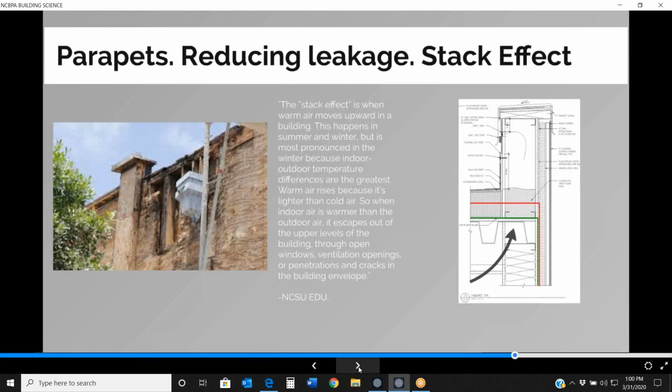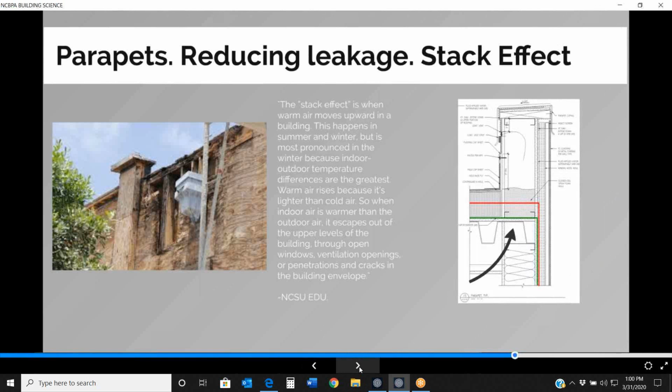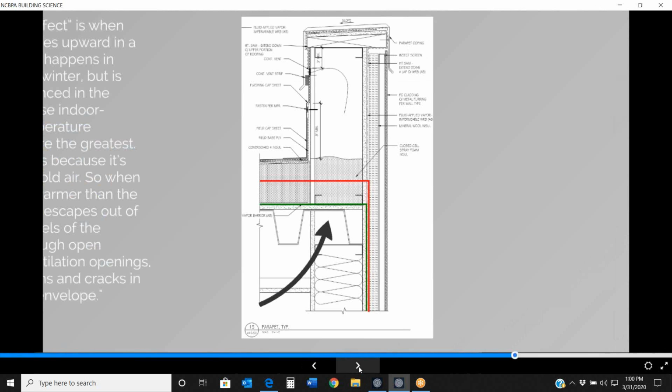You can see here in the detail, and I think we zoom in a little bit, what we're using to make our parapet conditions. So transitioning through insulation types to maintain our thermal control layer, reduce some of that condensation risk, but then also taking our vapor barrier, and in this case our air barrier, and extending it through to kind of close that off from air leakage.